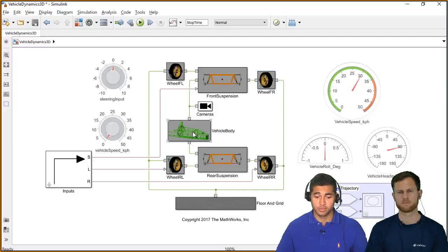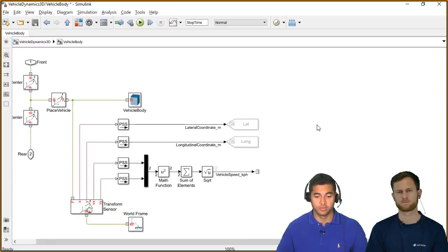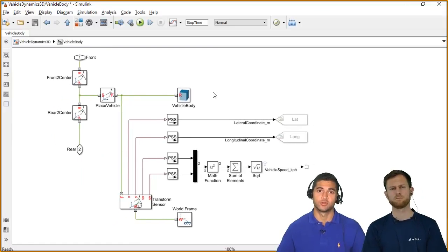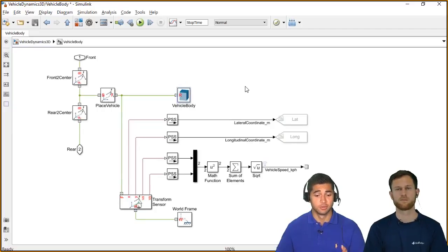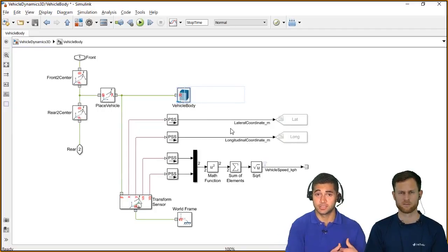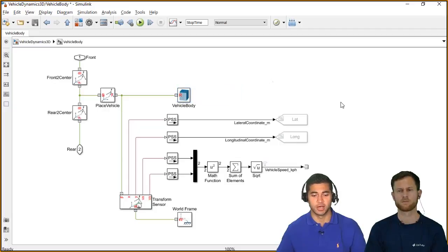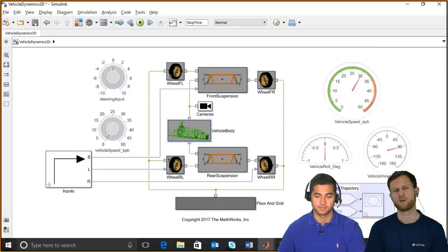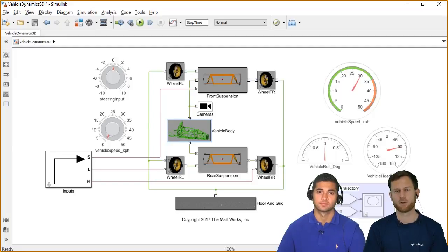Nice. Another thing that I want to show is pretty much how we're doing the body geometry. And what I did for that vehicle body, the green body that we saw in the animation, is I'm simply bringing a step file from my CAD software into this vehicle body. And that's how I'm bringing that geometry into Multibody. Yeah. Well, that's a very nice example. And well, teams watching that video, feel encouraged to upload or import your own CAD geometry of your chassis. I think that creates a lot more fun when working with that simulation.